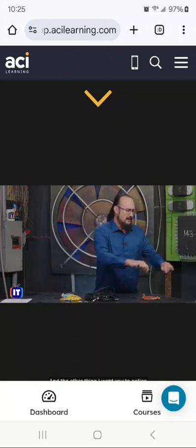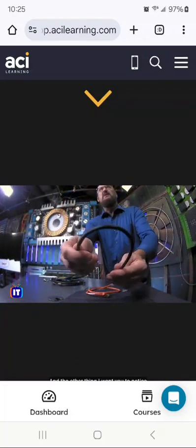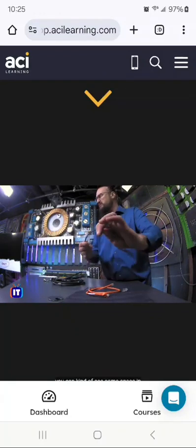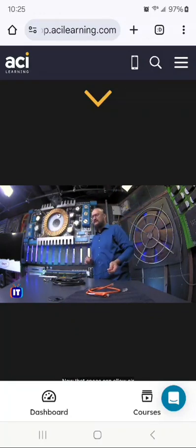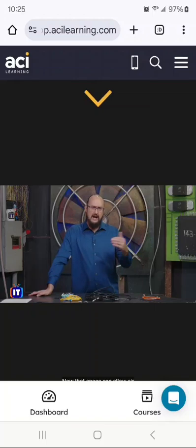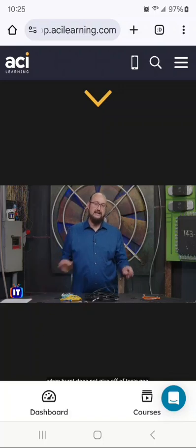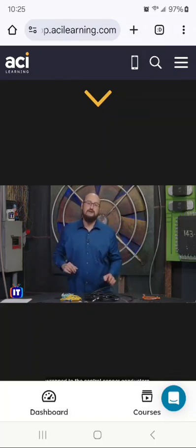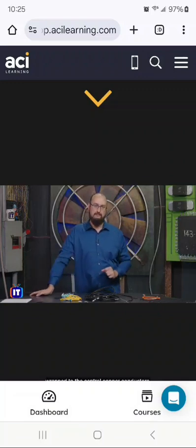And the other thing I want you to notice about this cable is it's very easy to work with, right? And you can kind of see some space in between those connectors right there. Now that space can allow air to pass through it, all right? And if you need to run cabling that will pass fire code and fire inspections, that when burnt does not give off a toxic gas, and whose jacket is really tightly wrapped to the central copper conductors, then that's where plenum comes in.